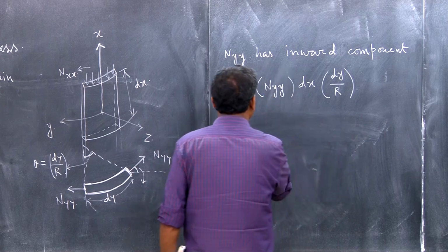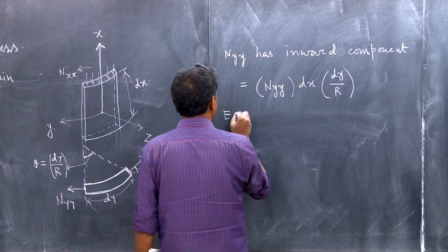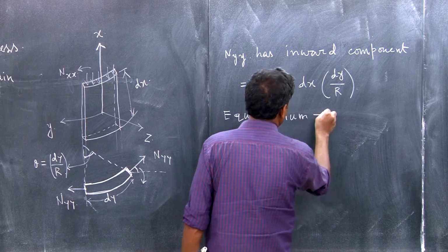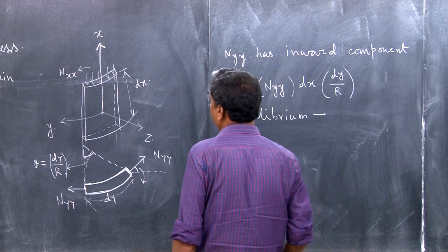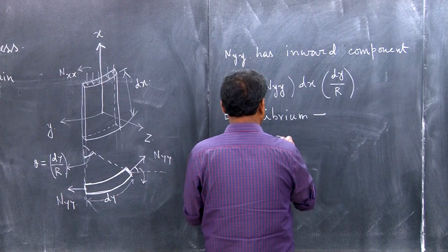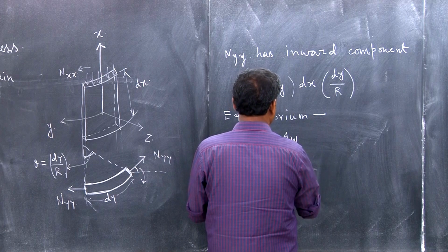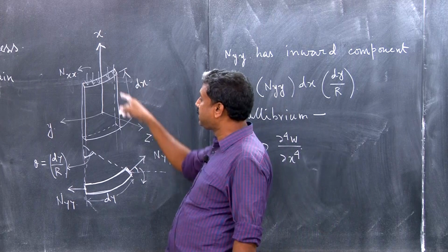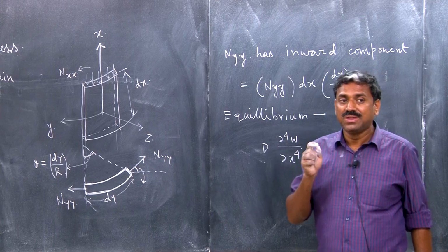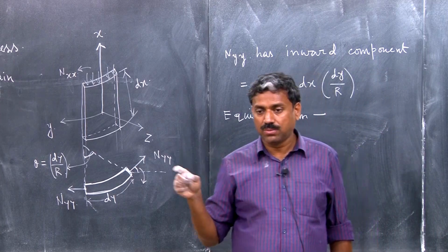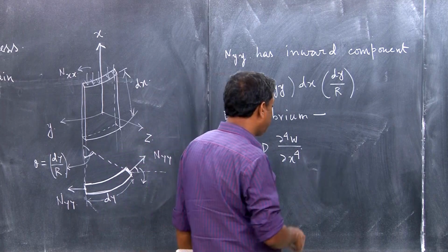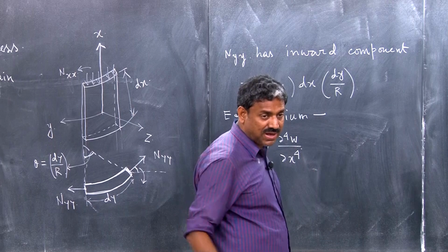So you can write down the equilibrium equation. We will take help from what we derived earlier. The bending is only with respect to the x axis, so I will not include the other terms. You saw that the term with the square of the Laplacian of w was derived before, but here the bending is only with respect to x, so I will only include this term.